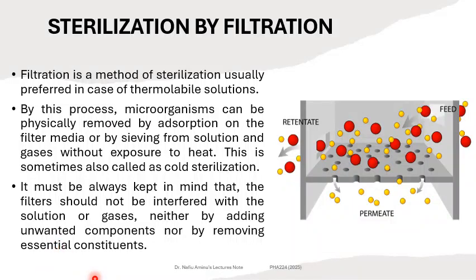So this process is such that microorganisms can be physically removed by adsorption on the filter media, as shown in this illustration. You see the bigger black dots, they represent microorganism cells. They are physically retained on the surface of the filter media. So the other content of the solution, maybe some drug content in ionic form or in molecular form, is the only thing allowed to pass through the filter media, by sieving from solution and gases without exposure to heat.